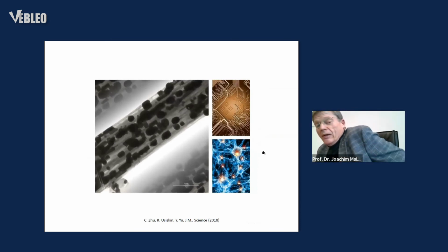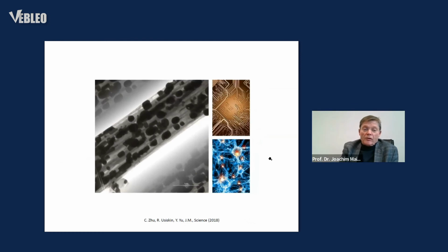And everybody knows, if you have a certain material, to say this is a good electrode material is not a good term, because it depends very much on how you shape it, how is your distribution in the electrode. So I give you here one example that shows it very nicely. This is tin in carbon tubes. Tin is a very good anode. In principle, it can store a lot of lithium, but it cracks because of volume expansion. But not so here. We have tiny tin particles that are mechanically separated, so there will not be any crack.